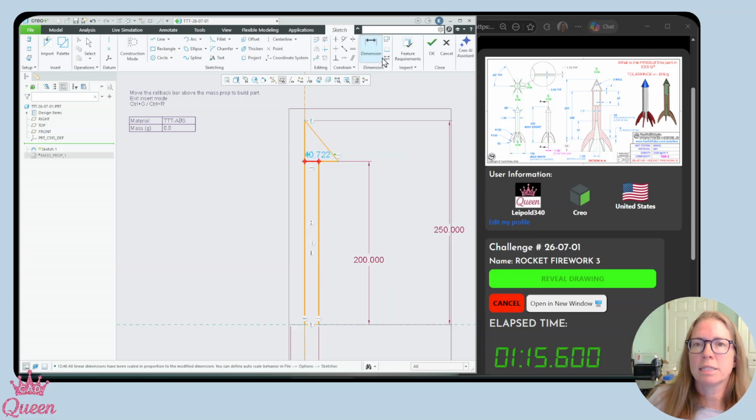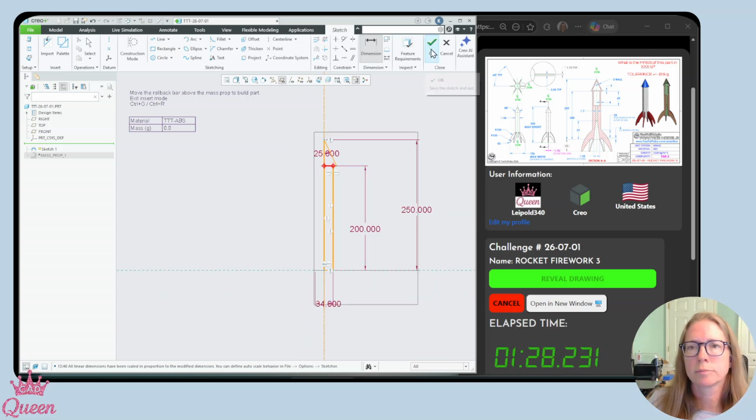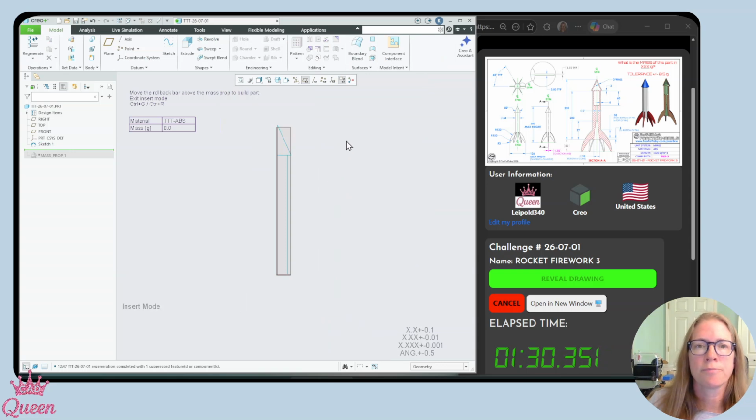The last dimension I need up here is the angle, and that's going to be 50 divided by 2. So that one's not as easy to set up, but 50 divided by 2 is that angle. Okay, so that's just a sketch. I'm going to change my filter down here to be sketch region. The alternate option there is to do Shift S, and that'll switch to sketch region.